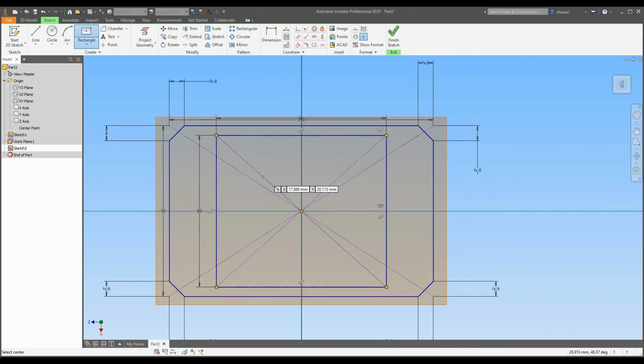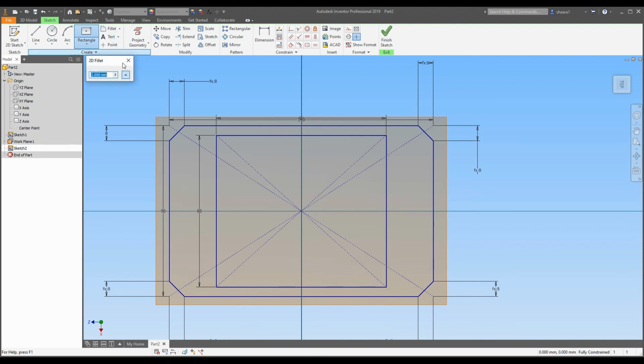And like I said earlier, I don't like making rectangles with sharp edges very much. So this time, just to change it up, I could use a chamfer again, but I'm going to use the fillet. You might find that it's actually easier when you're designing, if you know you're going to apply fillets or chamfers to any sort of shapes, to do those within the sketch, because due to how all the features build up in your model tree here, you will have to wait until the very end if you're going to use a feature, like a 3D modeling version of the fillet or the chamfer. I can explain that a bit later.